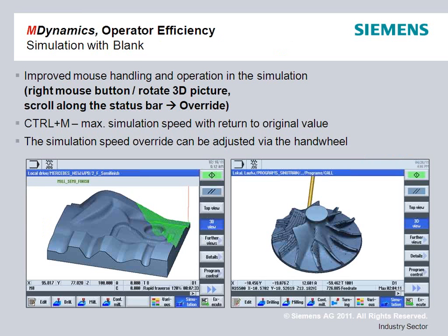In terms of other things that he can do, when he's programming at the machine and wants to make sure that what I told the machine to do is actually going to happen, if you have a reasonable piece of stock that's basically rectangular or basically cylindrical, you can simulate a full program. You can even simulate a full 5-axis program, and it will show you what effects the shaft of the tool is having on the part.